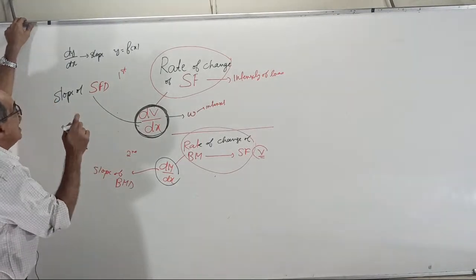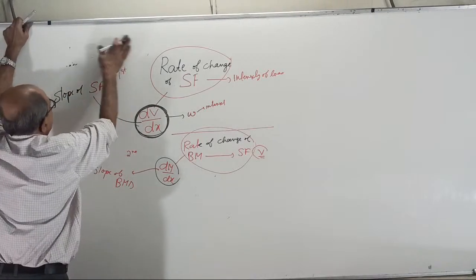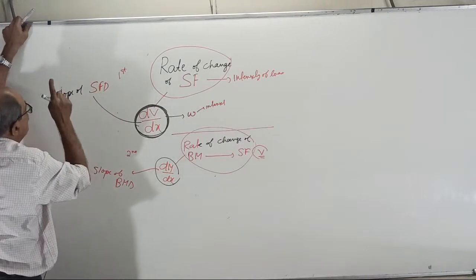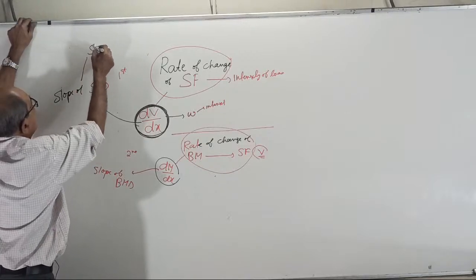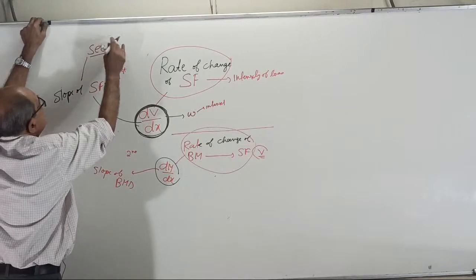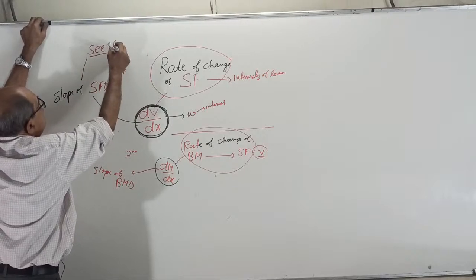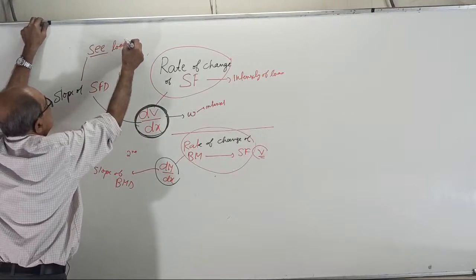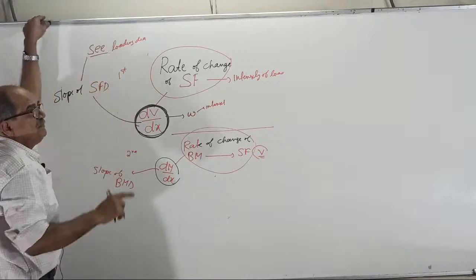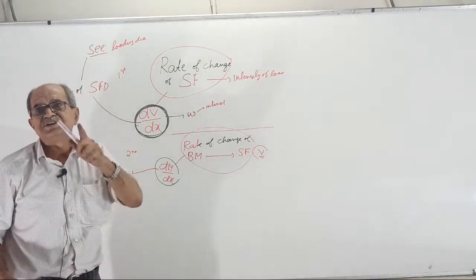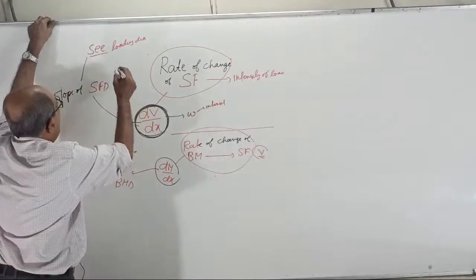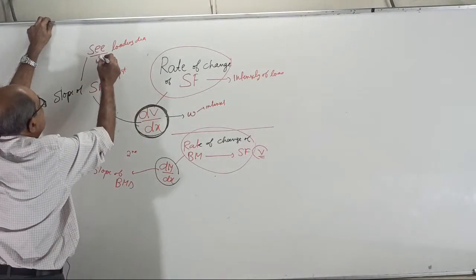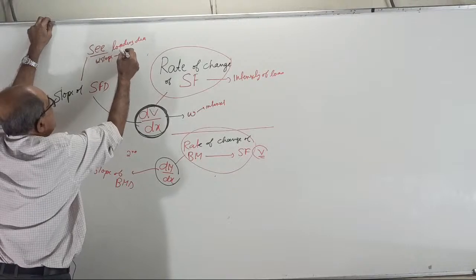Remember, if you want to decide the slope of the shear force diagram, see the loading diagram, and slope equals intensity of load.